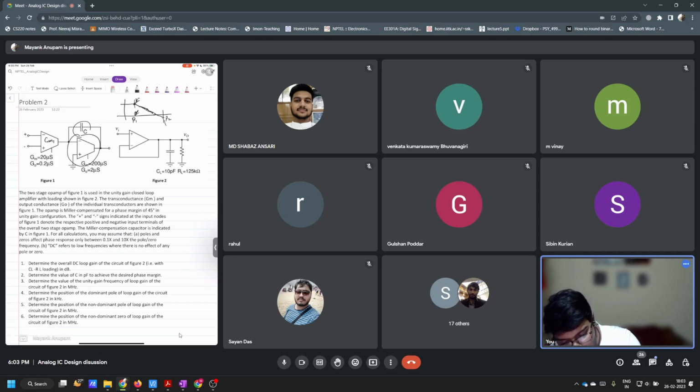And P1's location is, we say that it is because of the amplification of this capacitor C by the Miller factor, right? That we say, but strictly speaking, that is not the case. But all these approximations hold as long as this second transconductor GM2, its unity gain frequency is larger than the unity gain frequency. This is not strictly true because it is indeed a frequency dependent gain, so that is not true.